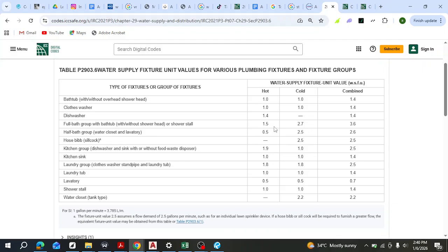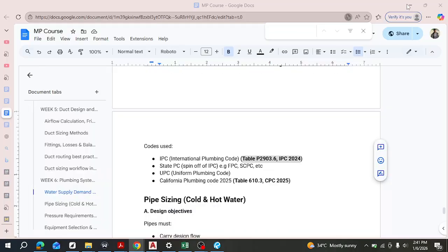And then if you notice too, there's the hot water side and the cold water side. Not everyone has both. Let's see. WC does not have hot water. Those big two are just like a regular tap, so they don't have a hot water value. But the rest of them always have cold water. You can see here that we have the dishwasher, which uses only hot water, and then this is combined. So we'll look at this again when we are designing a plumbing project. Let's move on.